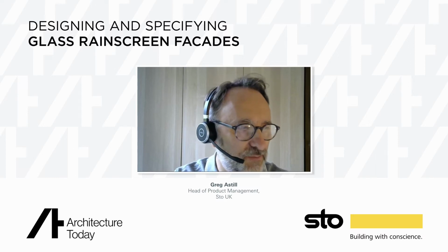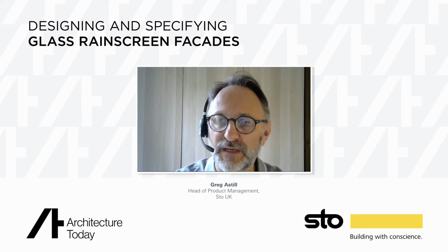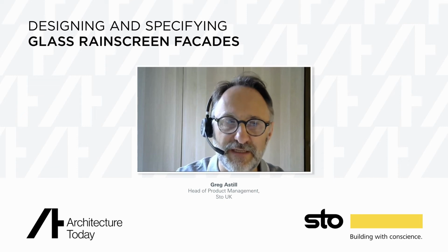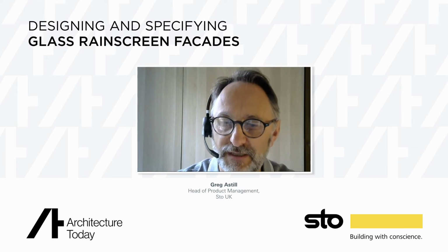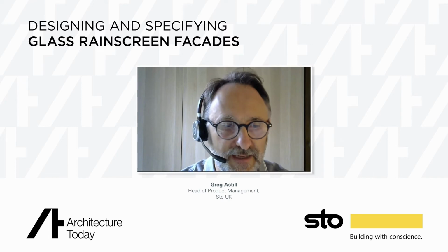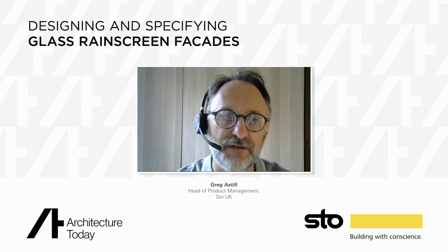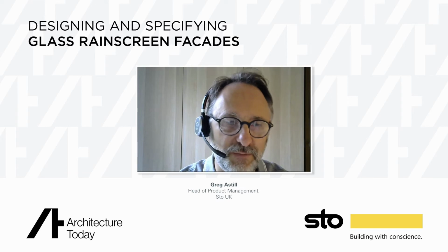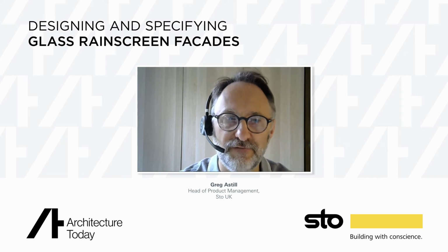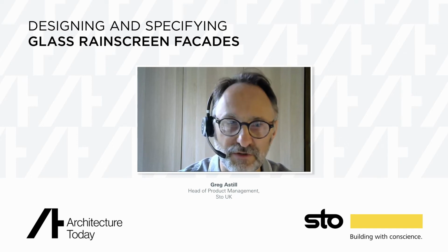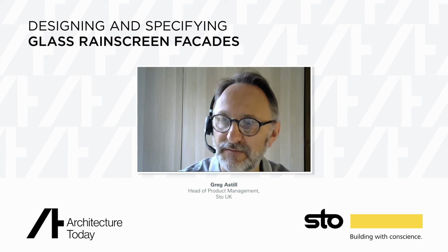It's quite important to distinguish between mineralic and organic pigments. Typically, organic pigments you'll find in paints, renders and things like that, or in plastics even. These are the sorts of pigments that in sunlight or intense UV will start to fade over time. Mineralic pigments don't do that. Mineralic pigments are particularly stable, so they've got a very high UV resistance, and you won't see colour fade over time, even under the strongest influences of sunlight.